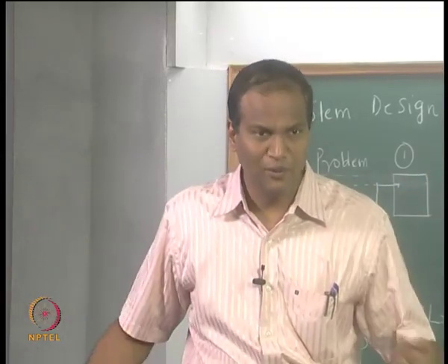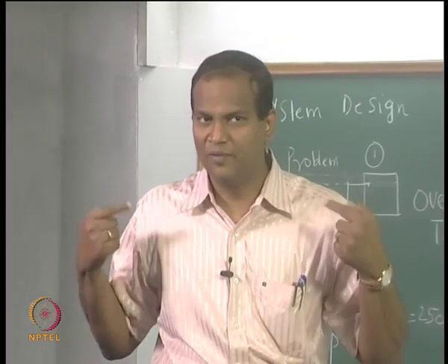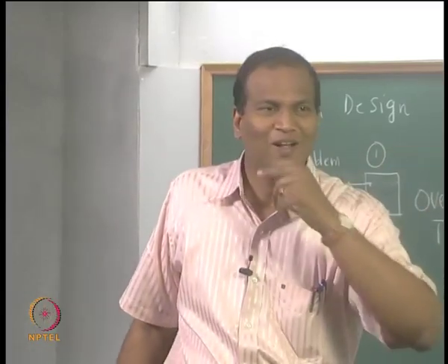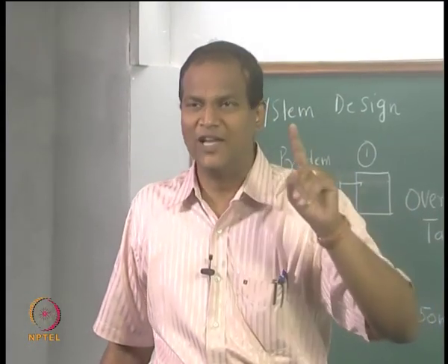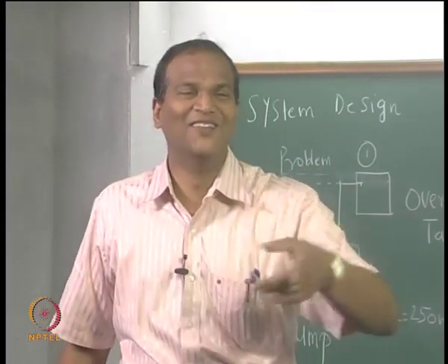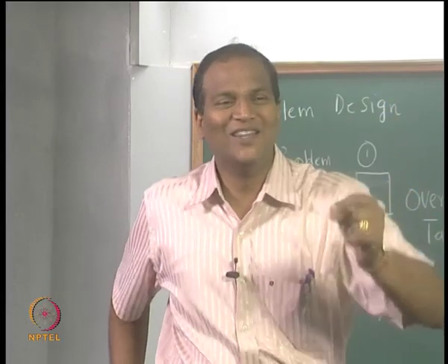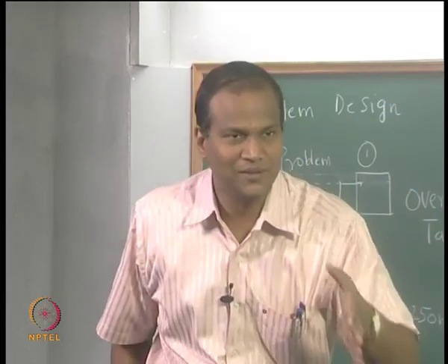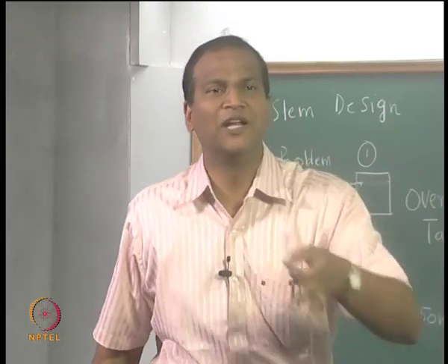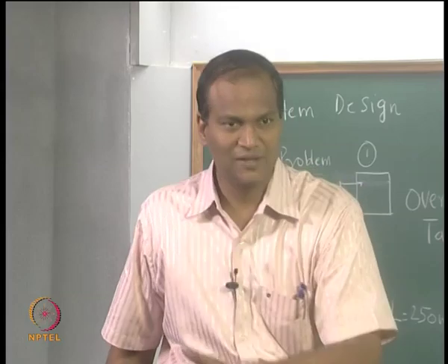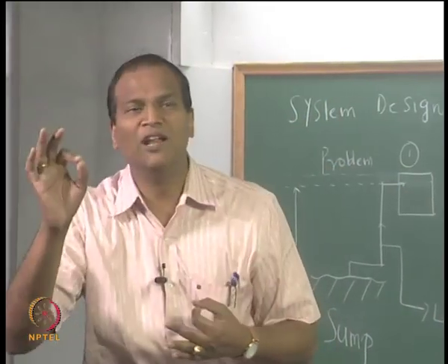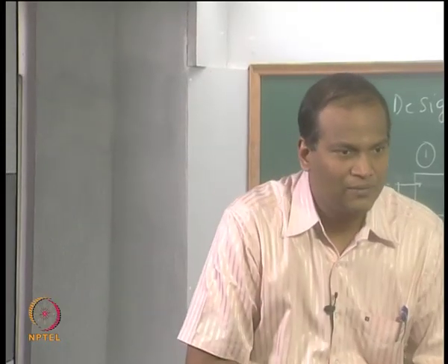on that, okay. And there is something called, I am totally diverting from the topic, but it's okay, we can cut it later. But still all these things have to follow what is called ETOPS. I am now deviating from optimization, I am live on air. All these things have to satisfy what is called ETOPS, extended twin engine operating performance standards. So if a twin engine has to fly between 2 cities, it should be within 180 minutes of the nearest airport on which it can land, okay.